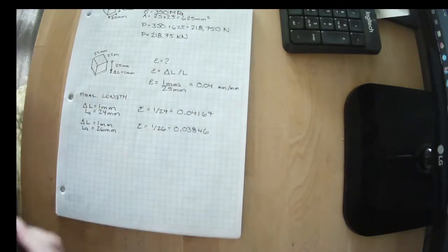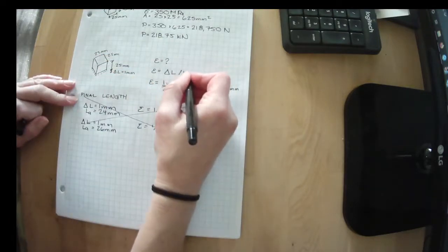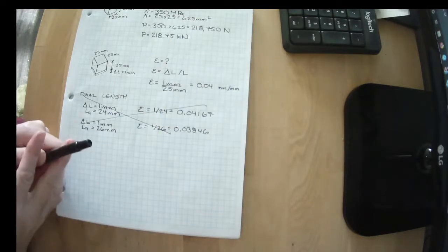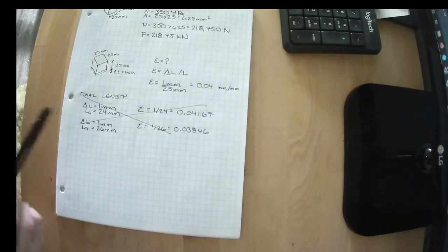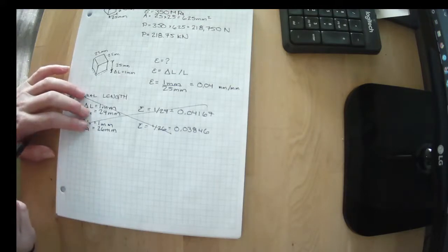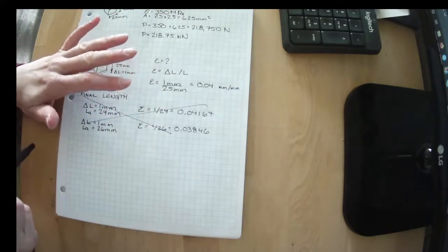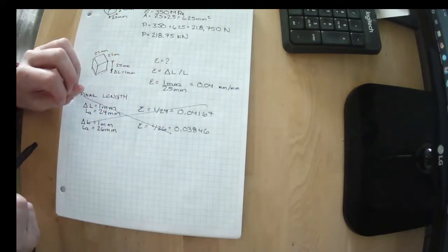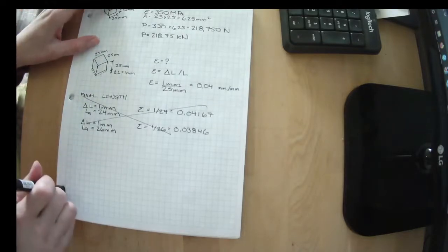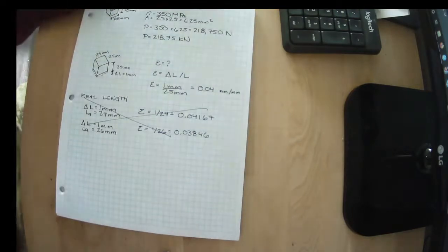So, a long time ago, everyone said, let's make sure we use the original length to analyze these calculations. You're going to do one in the assignment where what I want you to see is not the difference between tension and compression, but just how little the difference is between original and final length when we're talking about these kind of large-scale object calculations. Just to give you a sense of how small these movements are.